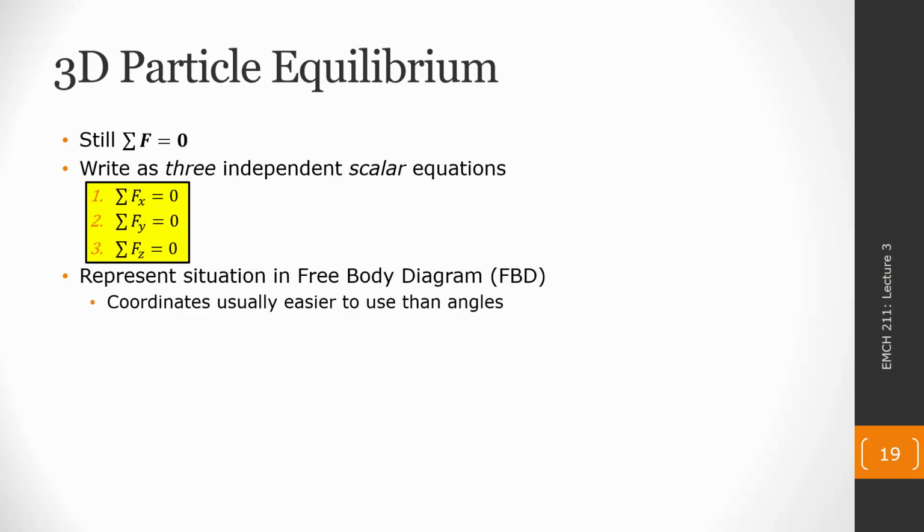But when we look at the dimensions, that 4th step, I really recommend when we're in 3D, you don't try to include angle measures in your diagram. Just putting coordinates of important points is typically going to be a much easier way to go, because we're going to use those coordinates to find position vectors or displacement vectors that we're then going to normalize to find unit vectors.